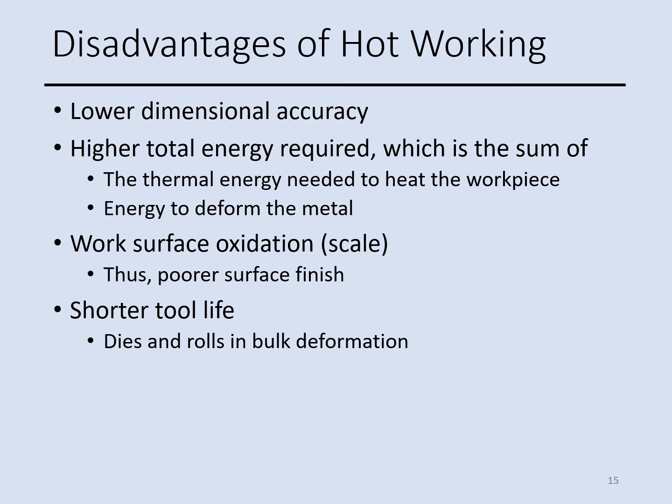Oxidation may happen if the part is exposed to some gases in the atmosphere, which is not favorable, for example, nitrogen. Then you will have a poor surface finish, and the tool life in hot working is shorter.